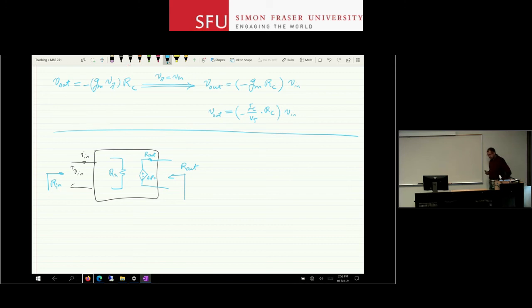But in terms of theory, how do you calculate these input and output resistances? Well, you take your circuit, make the small signal model. It must be small signal. Make the small signal model there, and then the issue is very easy. The input resistance R in is the equivalent input Thevenin resistor. The output resistance R out is the equivalent Thevenin resistance at that port. So this is V out and I out, right?